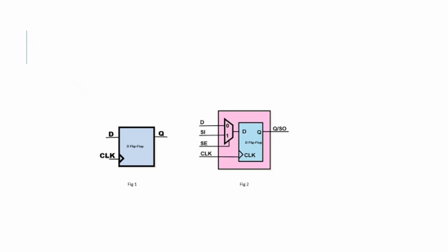Now the main process of DFT is converting the normal flip-flops in the design, that is the sequential elements, to scan elements. There can be multiple methodologies. It can be muxed scan, it can be LSSD based, or any other. We have multiple methods to convert, but this process may not be as simple as we think. It requires a lot of DRC cleanups, which are called scan DRCs.